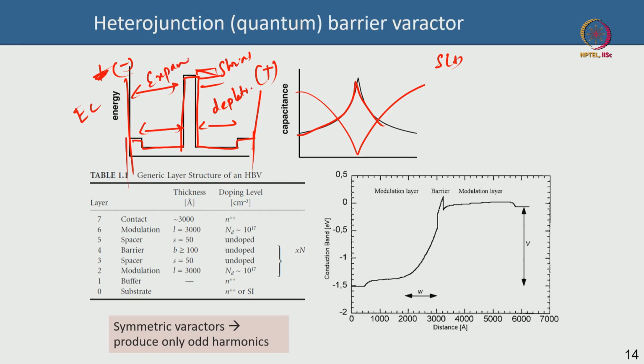So, there are two depletion regions in series, two depletion capacitances in series, this is C1, this is C2. So, no matter what you do, your capacitance will decrease. The maximum capacitance occurs at 0 voltage; either at +1, +2 or at -1, -2, your capacitance will decrease, because as I told you there are two capacitances in series, one is going to expand, the other is going to shrink, and it does not matter whether you are applying negative voltage or positive voltage on either side.